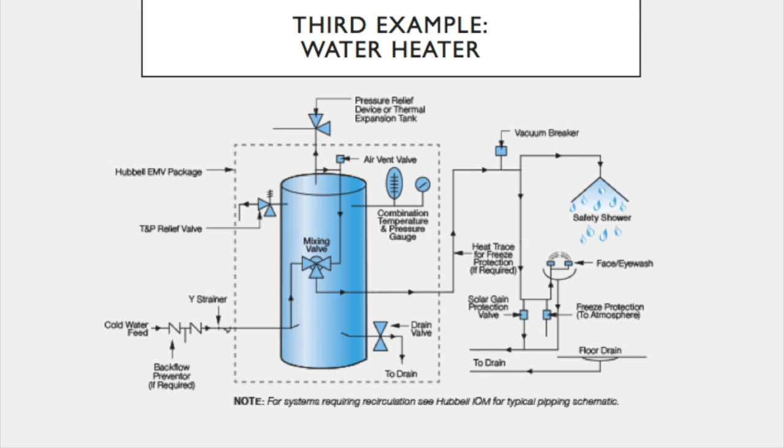The supply pipe of the heater routes cold water to the bottom of the tank through the dip tube. The hot water delivery pipe takes water from the top. All water heaters have a valve that will open if either the temperature or pressure of the water exceeds a safe limit for safety precautions.